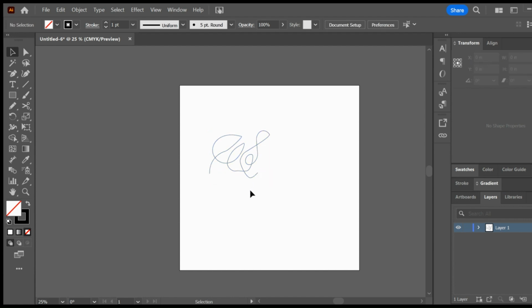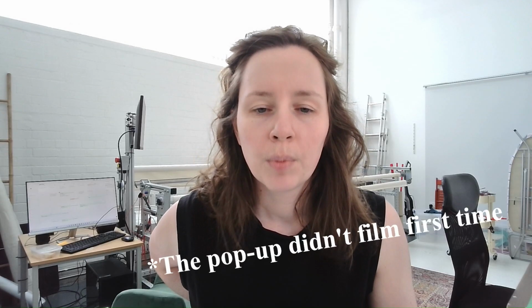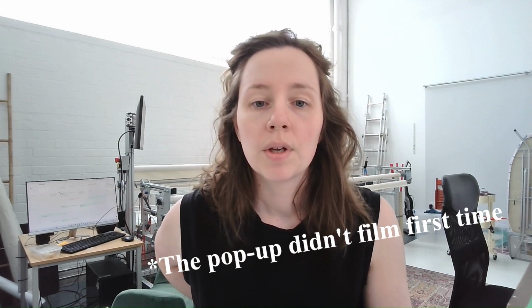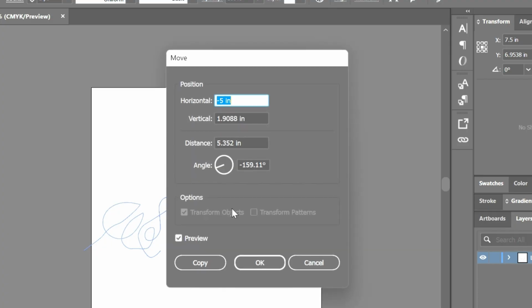Now you'll notice that is the basics of an edge to edge. If the start and stop point isn't on the exact same horizontal axis point, then your line is not going to repeat, and your software is going to say this is not an edge to edge. To repeat, I'm going to select the entire thing by pressing V. I'm going to press Enter on my keyboard. I'm going to move this along 5 inches, and then 0 vertically.